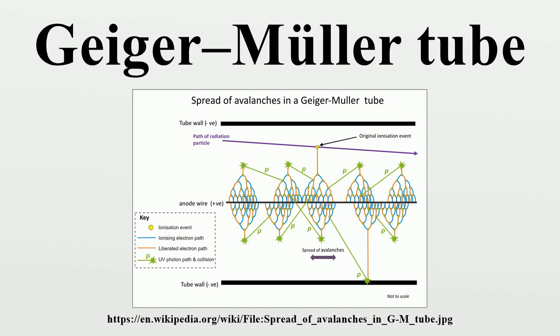If a poor diatomic gas quencher were introduced to the tube, the positive argon ions, during their motion toward the cathode, would have multiple collisions with the quencher gas molecules and transfer their charge and some energy to them. Neutral argon atoms would then be produced and the quencher gas ions would reach the cathode instead, gain electrons in excited states which would decay by photon emission, thereby producing spurious tube discharge as before.